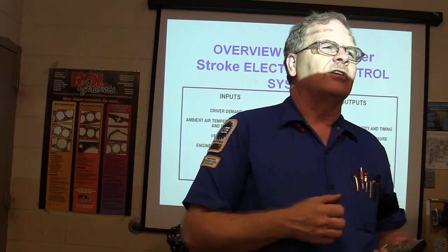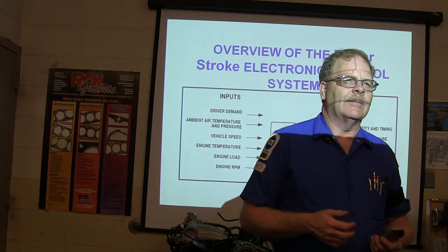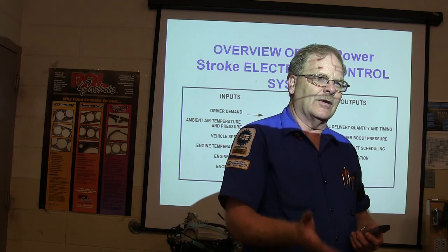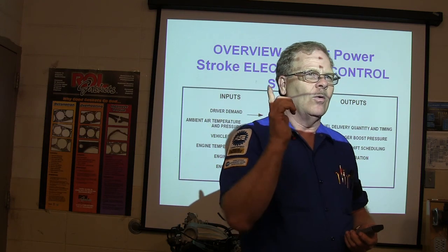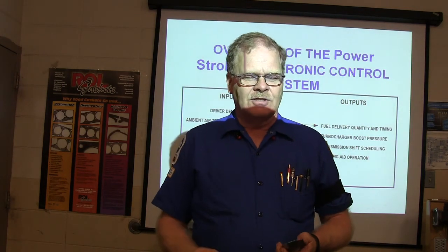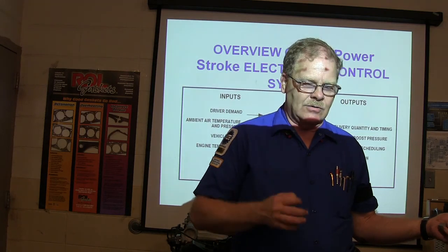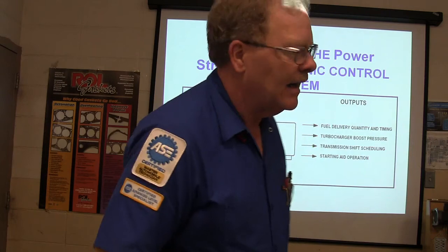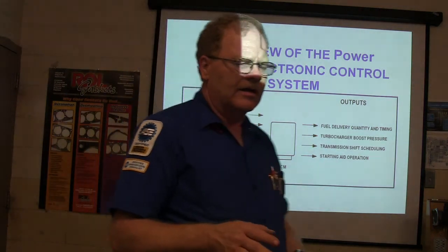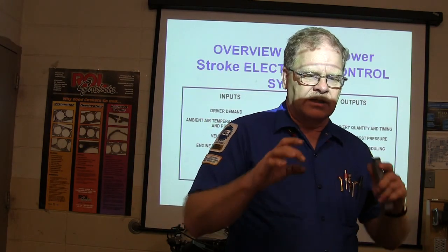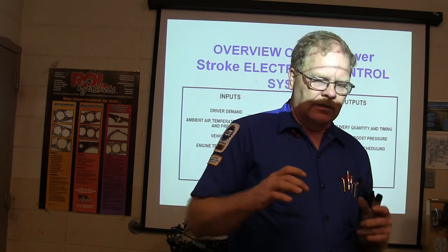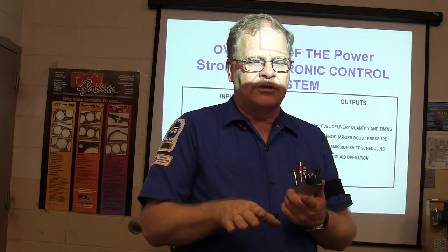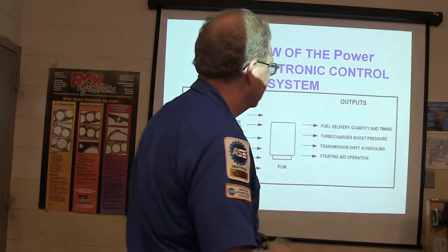What if I've got one cylinder that's skipping when I first start up, and I hook this inductive amp probe here, and I see that it's only pulling 175 amps? Well, whoa, one of these glow plugs is burned out. So what you do there is you hook your test light up to hot, and you check each one of them. Of course, you got to pull the valve cover off to do it the right way. Also, there's little harnesses, I think it's the 9930 harness, though maybe that's not the right number, that goes from the valve cover down in there to the injectors and a glow plug that's built into the valve cover gasket. Pretty interesting how that works.